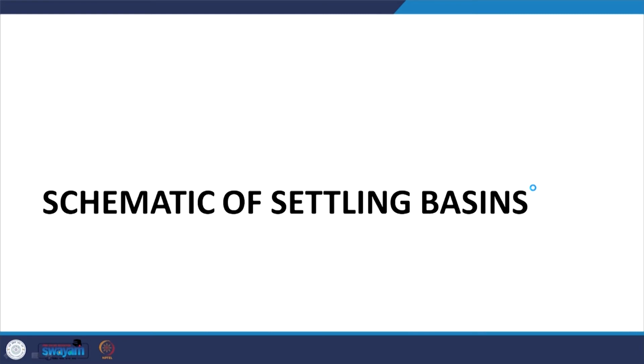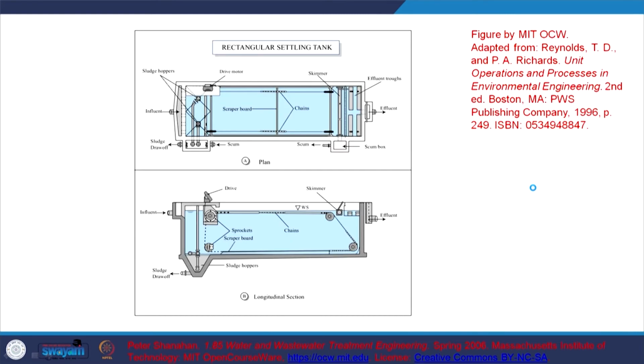So different types of settling basins, right? This is what we have. We already looked at the typical rectangular settling tank, but as we know, people would not typically prefer rectangular settling tanks because of maintenance-relevant issues. Think of this, you need long and narrow tanks, right? So all this area beside it is relatively difficult to utilize, right? So that's the relevant aspect.